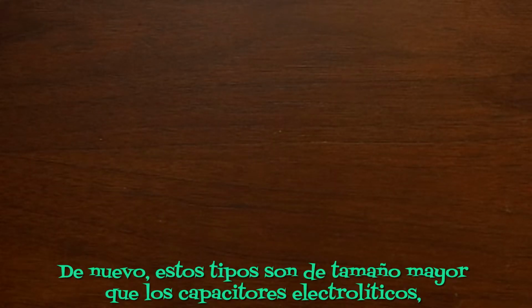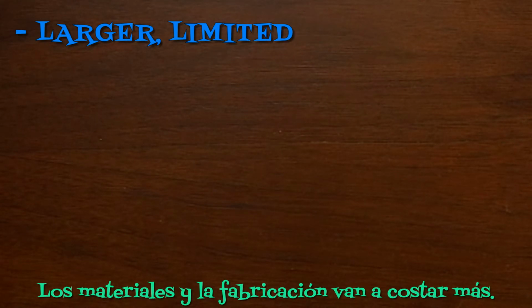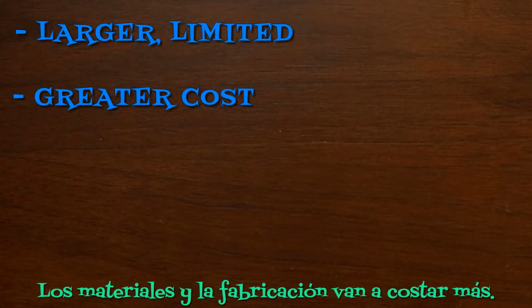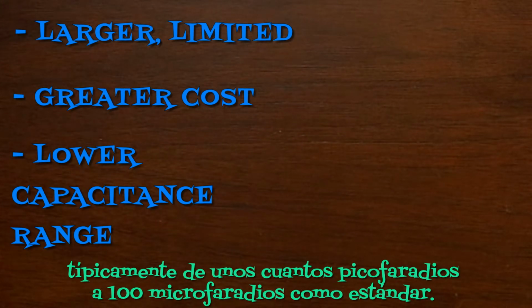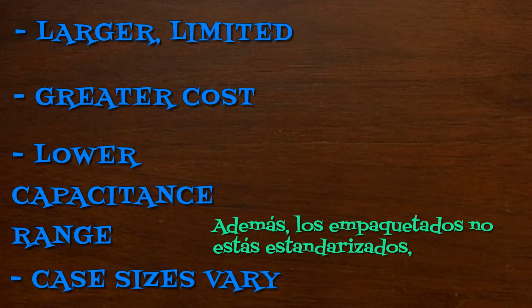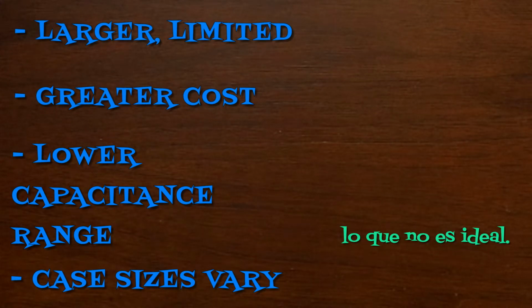Again, these guys are just physically bigger than your electrolytic caps, which could present some limitations. The materials in manufacturing are going to cost more. They've got a lower capacitance range, typically a few picofarads to 100 microfarads is standard. Plus, the case sizes aren't standardized. You've got different vendors doing different things size-wise, which isn't ideal.